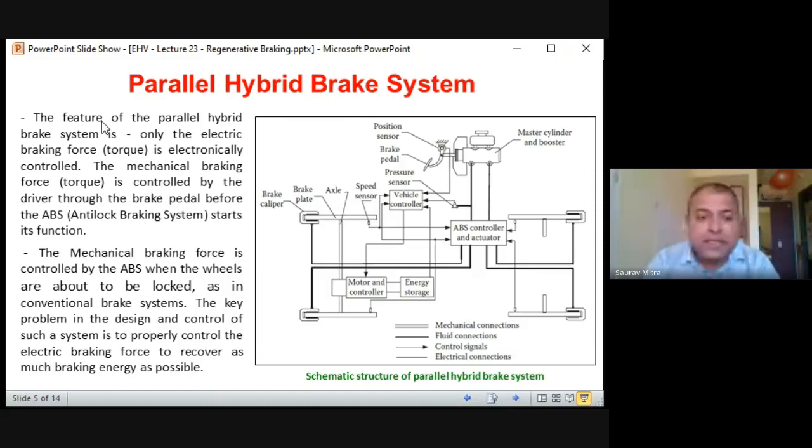ABS and TRC, you should understand very clearly, ABS is helping the car not to skid after it brakes. And second, TRC, traction control, generally comes into play where there is snow and such conditions. Whenever the car is trying to generate some tractive force, and there is snow, the tire keeps on rotating and slip happens, and the vehicle does not go ahead. In that case, the TRC system comes in and checks that part.